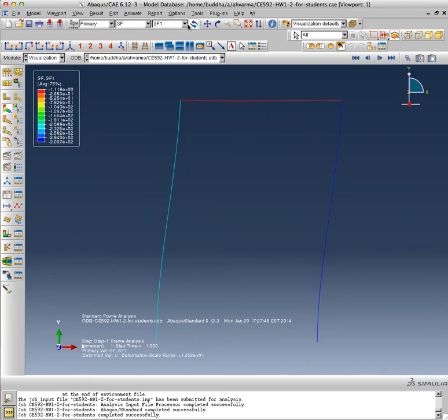And it has the options of plotting SF1 and SF2, both of them. Now, the problem is it's a contour plot. And what do you do with a contour plot? It's really hard, because I really wanted an axial force diagram for SF1. So in order to generate the axial force diagram, all you need to do is look at the contour options.